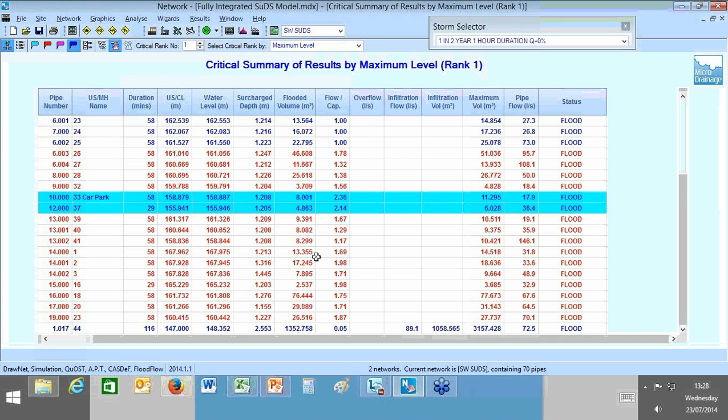So what I'm going to do now is show you how to set up the simulation criteria to replicate one of these worst case scenarios, 50-year, 1 hour storm duration with an additional 200% for climate change on the intensity of the rainfall, and then show where the flooding is going across the site. As importantly, make sure that we protect the properties. This isn't now upsizing everything under the ground. This is now surface water management.